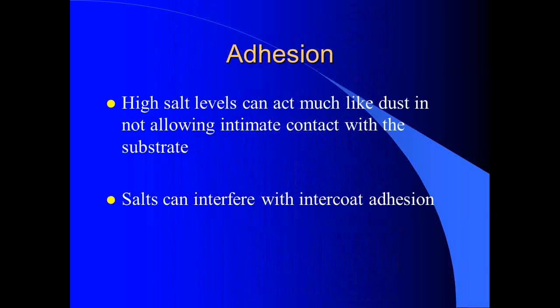Adhesion. High salt levels can act much like dust in not allowing an intimate contact with the substrate or to the intermediate coat. Well, we had a project down in the Florida Keys. It was a lighthouse down there. The engineer writing the specs was well versed on the fact that the salt-laden air had come in at night and contaminated a surface. He knew the lighthouse was contaminated, so he required it to be washed down with our salt remover, remove the salts.